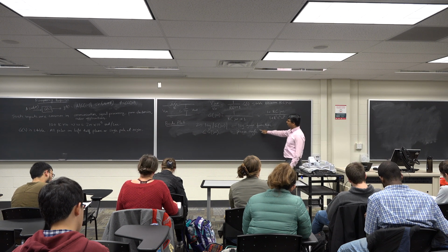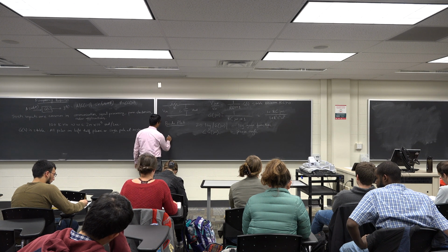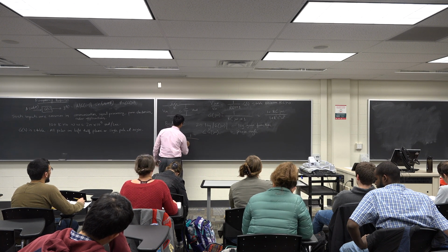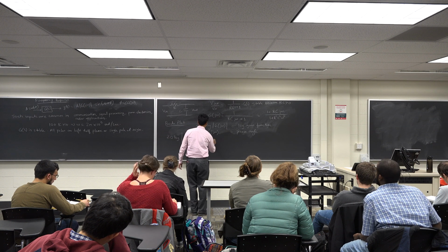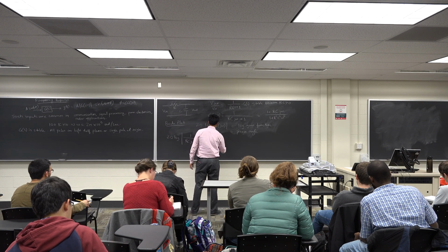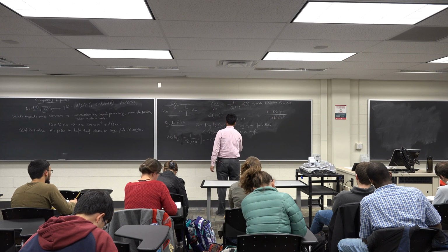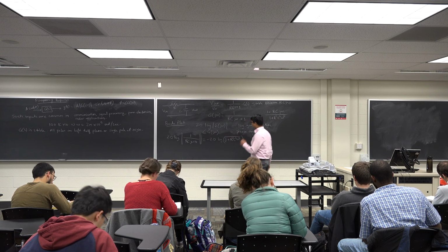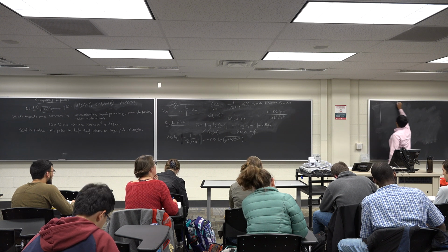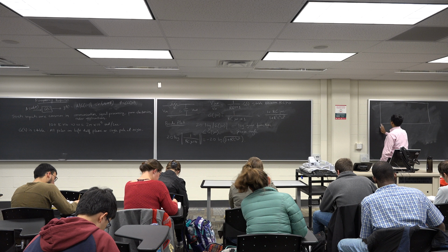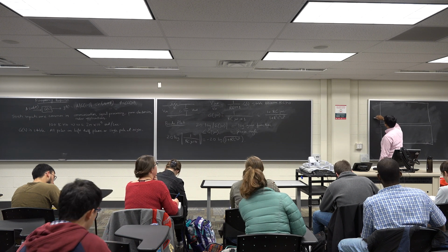What would be the log of the absolute value of G(j omega) for this system? Let's compute it. It is minus 20 log of RC j omega plus 1, which is minus 20 log of the square root of 1 plus R squared C squared omega squared.